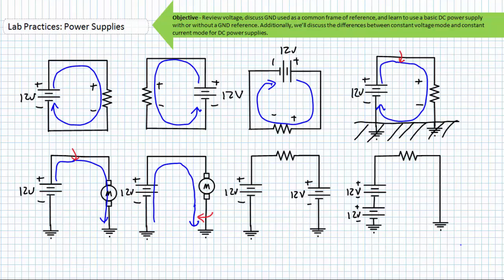In the case of the high side switch, our motor is connected to ground, and the switch simply enables it by connecting it to a voltage source. Hence the alternate term for this methodology, sourcing. In the case of the low side switch, the connection to the supply exists. The switch's only purpose is to provide a path to ground, and this is sometimes known as a sinking arrangement.